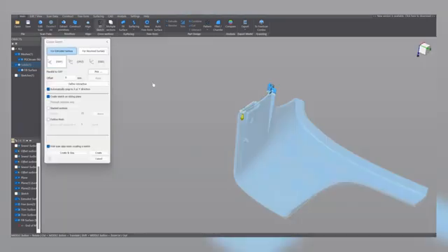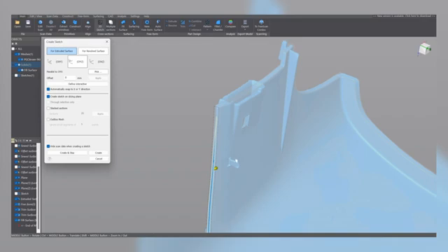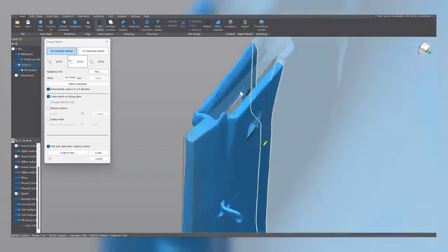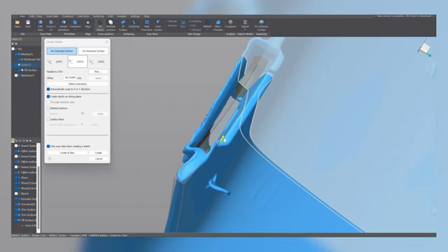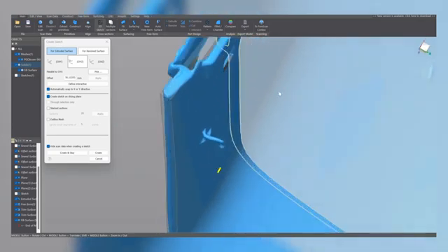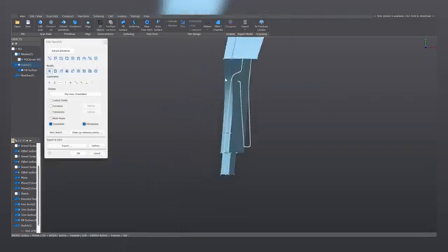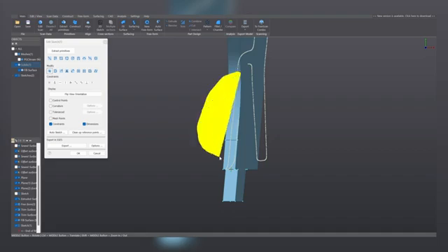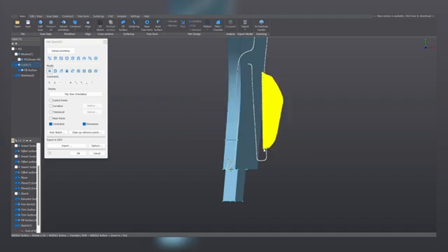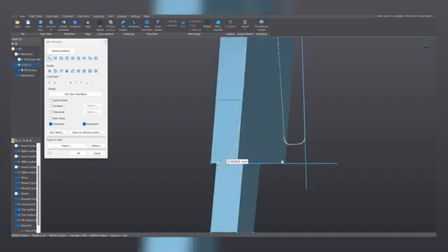And to do it, we start with a 2D sketch. We select the proper orientation, and we cut our mesh, or we slice it, at a position that gives us the information that we need. Make sure that Create Sketch on Slicing Plane is enabled for this case. We click on Create, and we start by best fitting a couple of lines here and there. We are going to extend them, sorry. And we are going to create a horizontal line on the origin of the coordinate system.